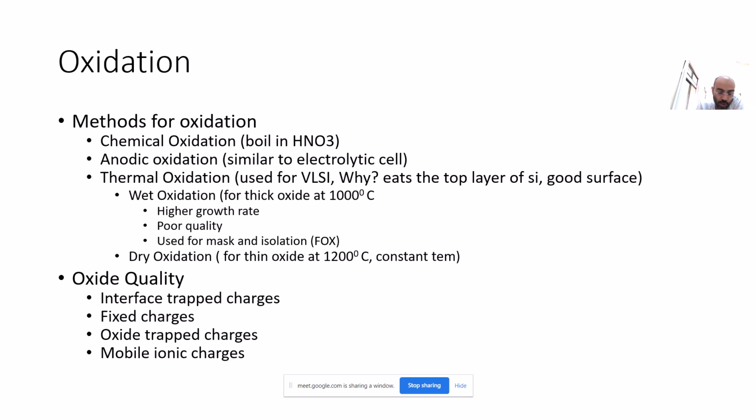They very much interact with your threshold voltage, and these mobile ionic charges should be least present. If they are at all present, then you use certain processing methods so that these mobile ionic charges should not be present. And the very simple method is that this oxidation is done in the presence of, rather than using the pure oxide, oxide with chlorine or with halogens, I should say. So chlorine or fluorine or bromine you use.